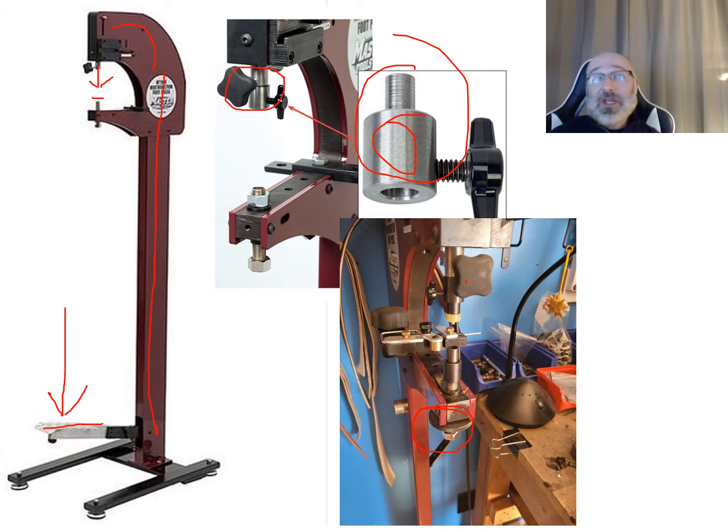So maybe you can get a hand set for one of these. You can set it all up and align it, and it's going to take you like a minute or two to put in a rivet. That's fine if you're making a couple of these as prototypes, no big deal. But all of a sudden, this cuts it down to 5-10 seconds each. Put the two pieces in, put your piece in, step down the foot pedal, go to the next. If you're talking about a large-scale production, something like this is very, very useful.